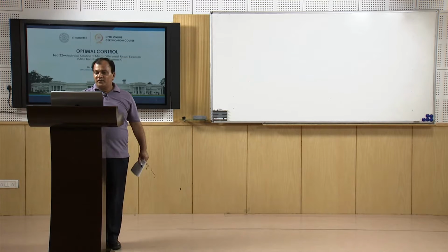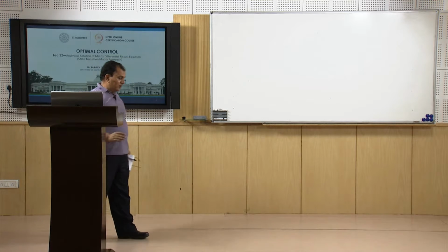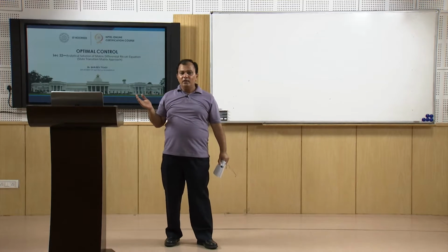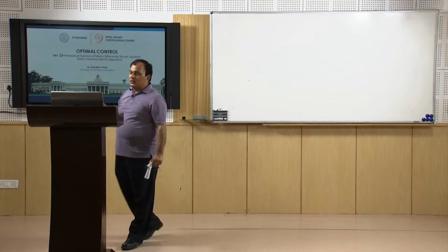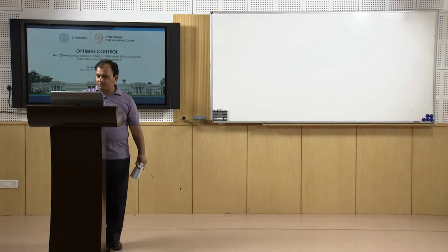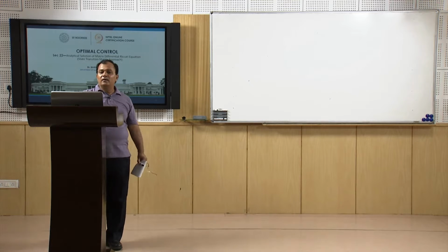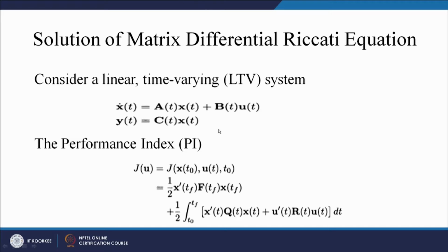So, by this state transition matrix approach we can solve the matrix differential Riccati equation or algebraic Riccati equation. So, first we will see how to find the solution of the matrix differential Riccati equation.